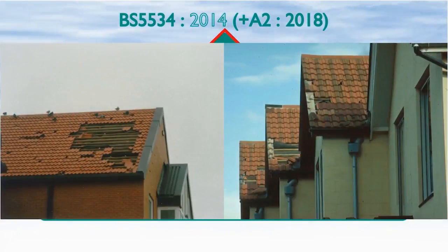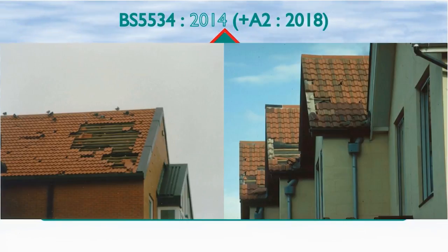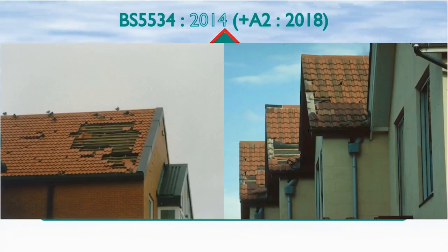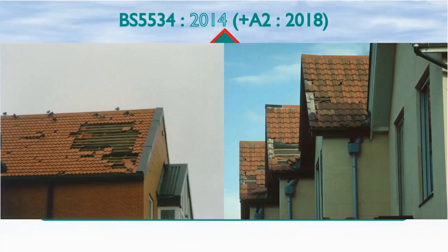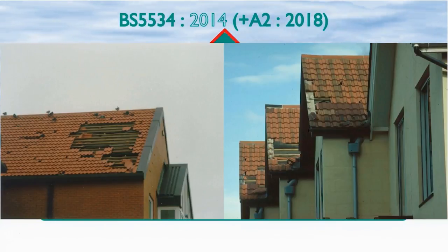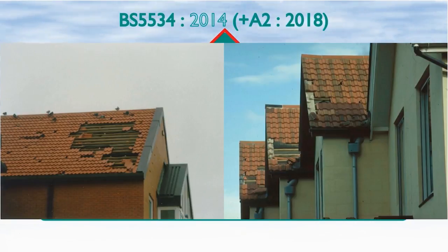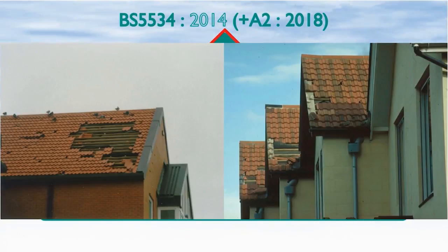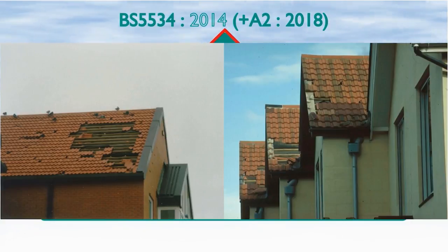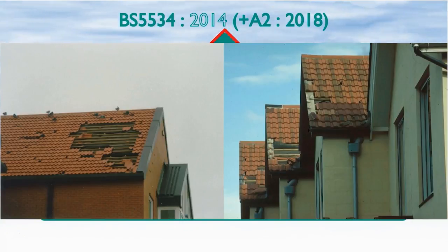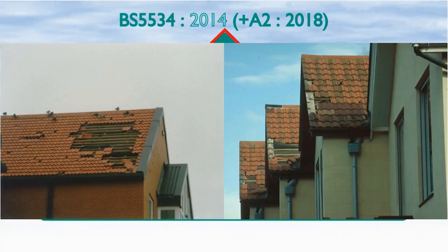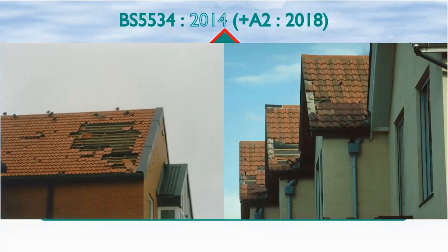If the roof is not correctly designed to resist wind uplift forces, then in extreme cases the tiles and slates or outer covering can be damaged. This damage will be mainly caused by uplift forces directly removing the slates or tiles by sucking them up and off the roof. In theory, it could also occur due to the underlay membrane ballooning and pushing them off, although there is little, if any, conclusive evidence of this occurring.